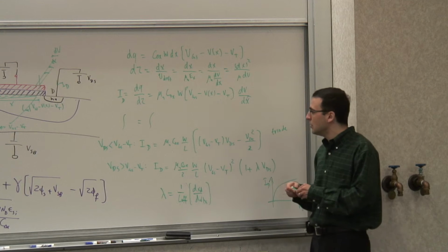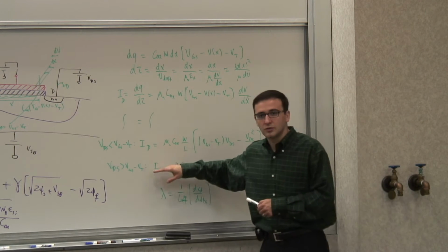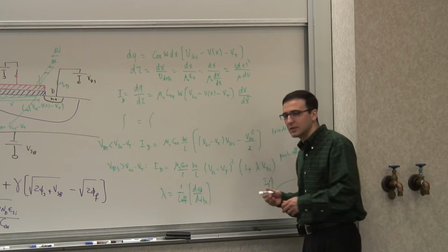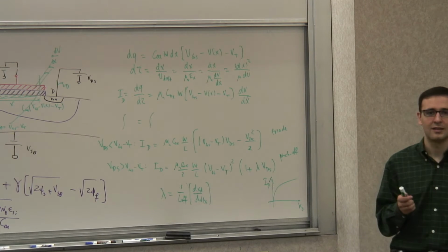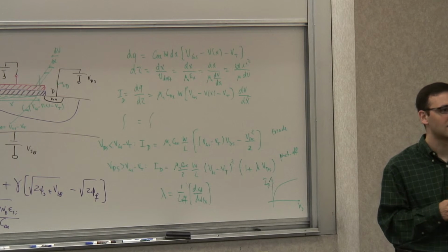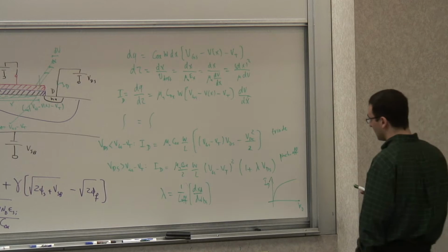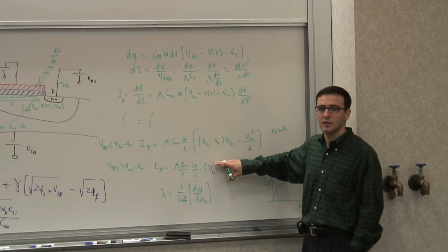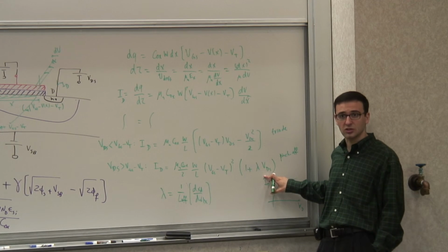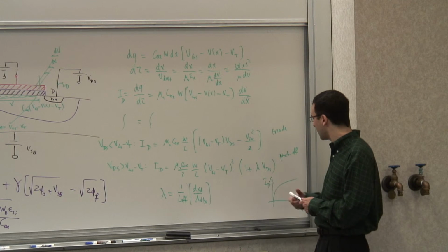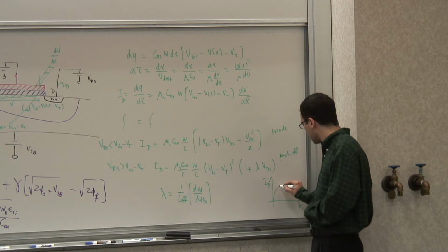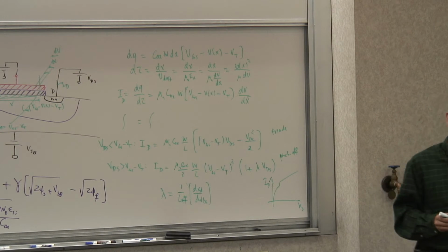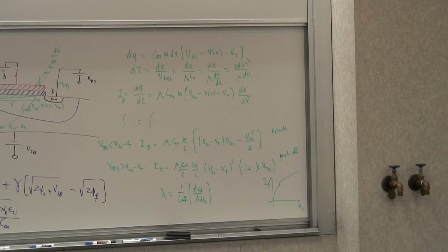Now, one side note, these were the two equations we had for the two regions, the triode and the pinch-off. If you look at these two, the way I've written them, there's a discontinuity at VGS minus VT equal VDS. Why? Well, I derived this part of the equation from that. So if I just drop this term, it is continuous, right? But now I've added this correction term that makes it discontinuous. So if you actually go and plot this, you will see something like this at that point, which is an artifact of this correction term.